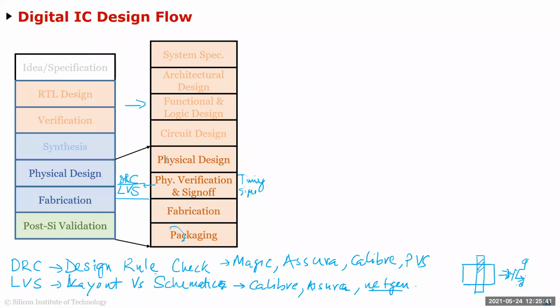And it is going to use that and still going to say that, yes, we are meeting timing. So it'll create a huge report. So usually there are a lot of physical verification designers. In India, for example, in VLSI design, probably the two biggest areas are the DV, the design verification in the front end, and the physical verification sign-off. And it doesn't mean you're just looking at the tool and saying, oh, it passes. This is where you need your timing knowledge.